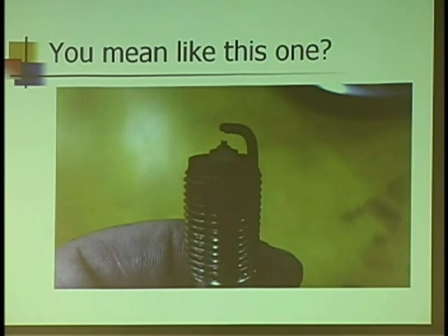Okay. And again, think. If there's more fuel, it's going to be easier to cross the gap. If there's less fuel, it's going to be harder. If there's low compression, it's going to be easy. Think you can do a relative compression off the secondary? Yeah, you can. You get a weak cylinder, it's not going to have a firing line anywhere near as tall as the rest. But because they vary quite a bit, there are a lot of other methods that I've already shown you that are a lot more accurate.